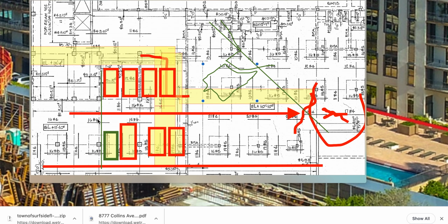This is our first fracture right here. This is our fracture line. Our fracture line is here. Smallest section here. Cars come in. They all are loading this area. These 8 cars every day are cycling this area here that causes the fracture. It develops the fracture. Okay, they come in, they stop their car, and they back up.